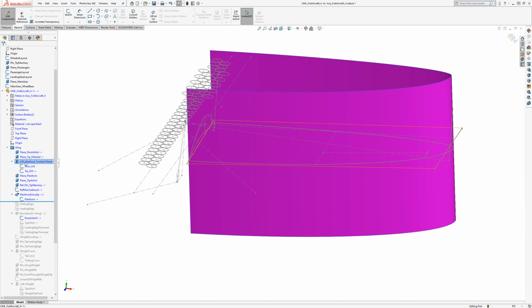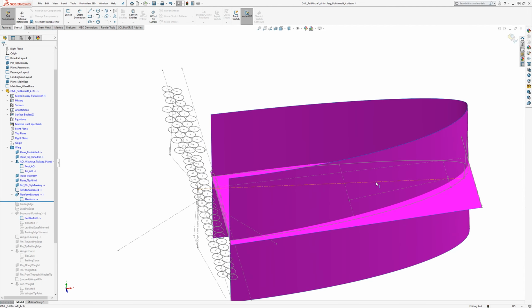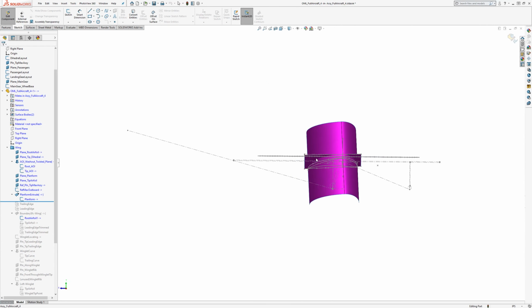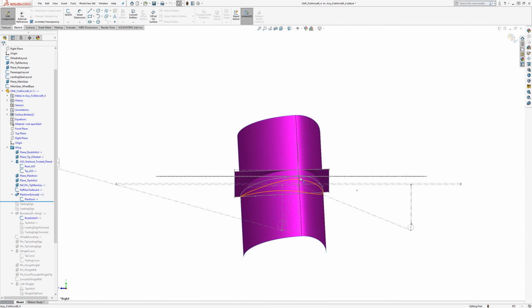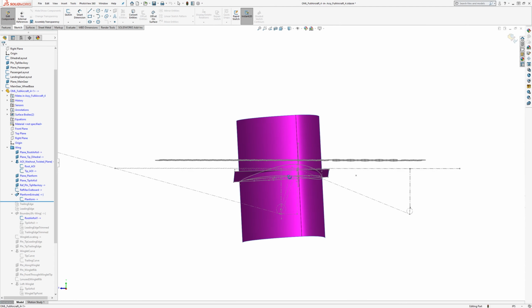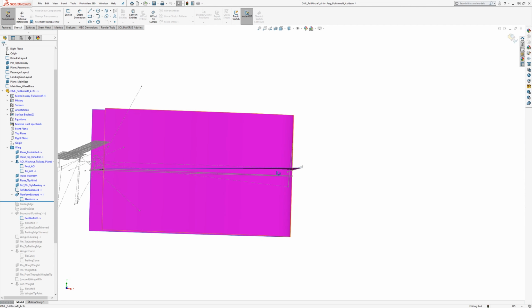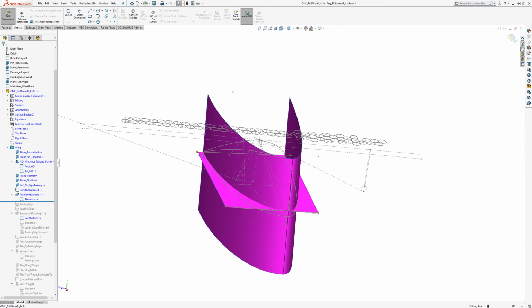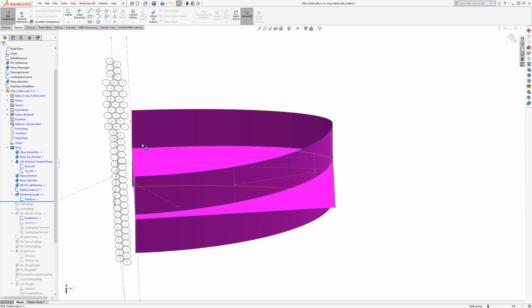So then what we have is two surfaces. One that's the planform and another that is this twisted plane. The planform is being extruded at this 3 degrees back and 5 degrees up dihedral, and this twisted plane is coming along as we saw before, and where they intersect, that's going to be our trailing and leading edges.